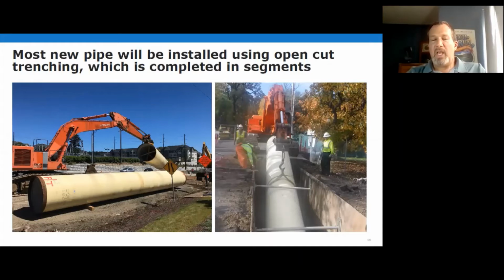After they get it welded, they backfill around the pipe. Around the pipe and to about a foot over the pipe is always rock material to provide nice compaction and hold the pipe in. Part of what gives a pipe strength is nice rock compacted around it.